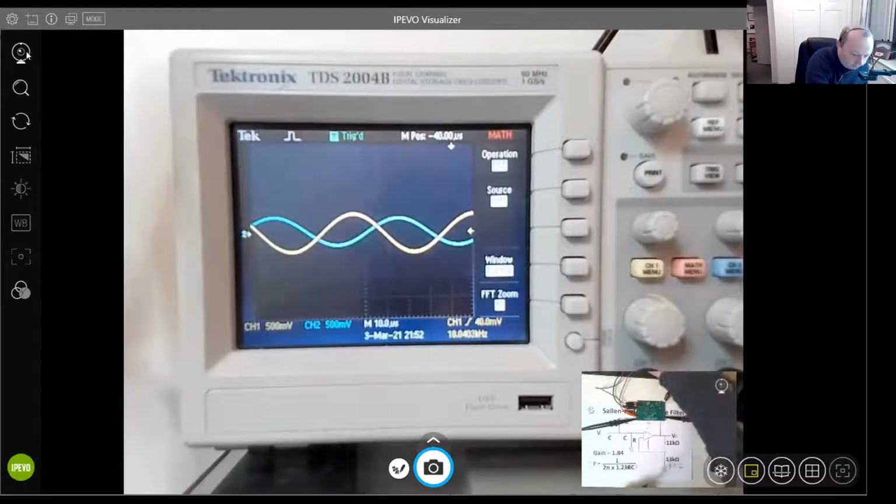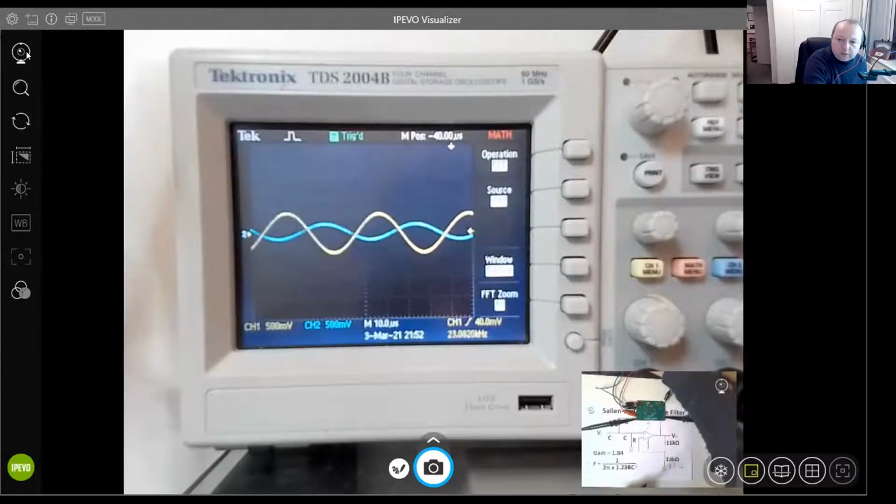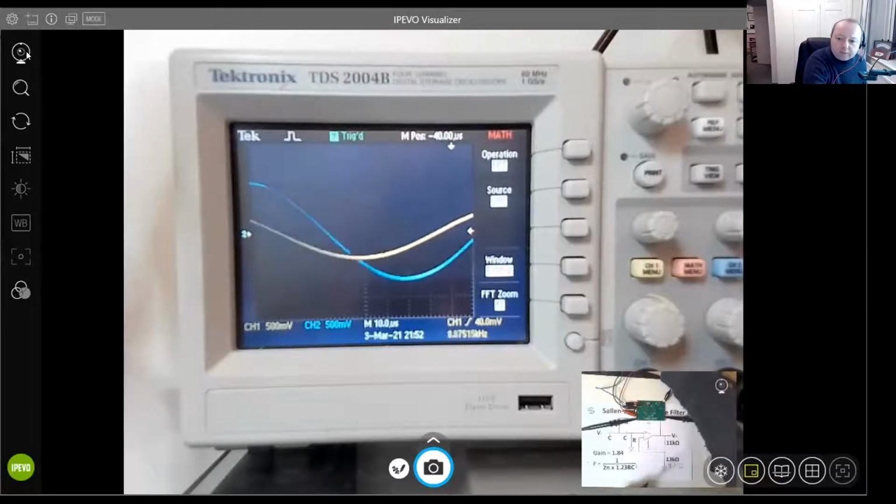Right. So to twiddle the right knob here. So there we go. So as our frequency goes up, see, we're starting to lose our output. So using an op amp as a filter circuit, yeah, you do get gain. So that needs to be taken into consideration.